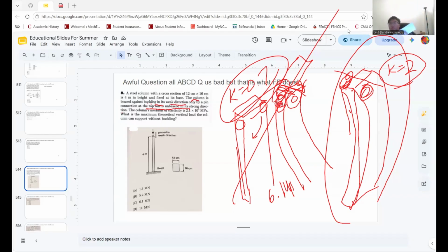I wish there was foam. The foam would be much appreciated. But the weak direction we already calculated. We need to calculate the hard direction, which is moving this and this way. So you can imagine by making this 3D thing, how to brace it. The bracing to stop the strong direction would be on the side. I'm drawing it wrong over here. It should be on the side. The stop braces should be over here, clamping on like this. And then we should be good.